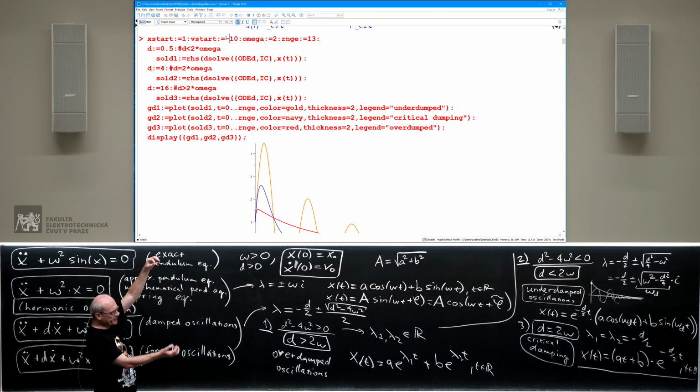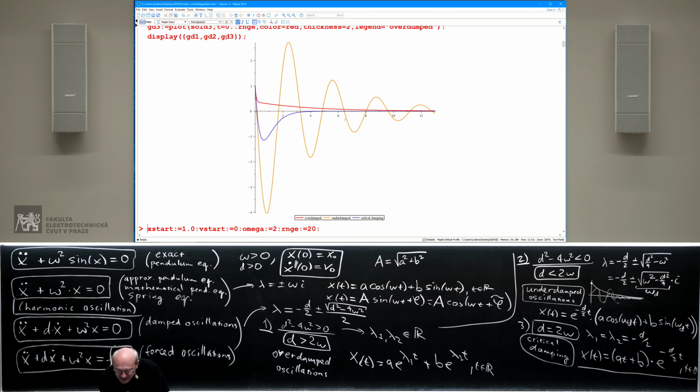So I pull on the spring, and when releasing it, I move it upwards. So I'm actually adding energy to the spring energy. It's as if I was strengthening the influence of the spring going upwards. So I expect the spring to overshoot a lot also when going down. Well, we will see over here. Wow, that's quite a bit of overshooting. So we started on the top, and then it overshot downwards. And then the harmonic oscillations, the gold curve, actually they go and settle down.